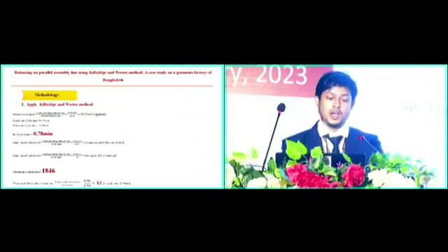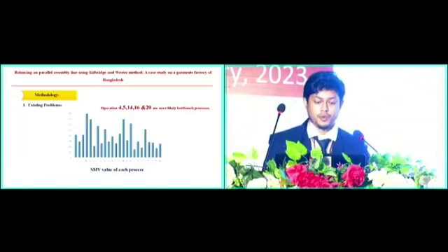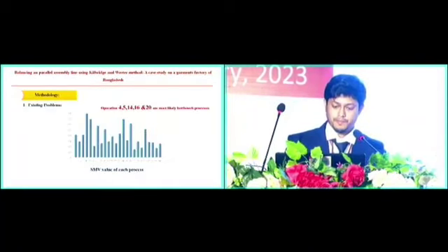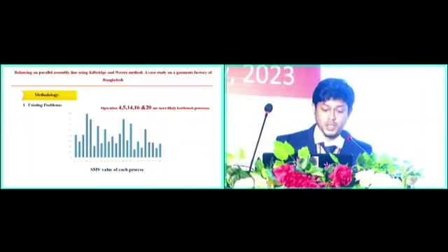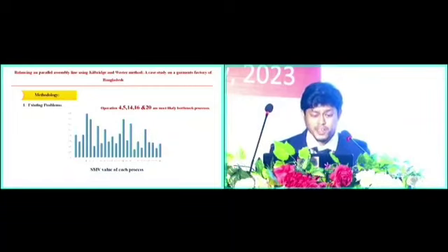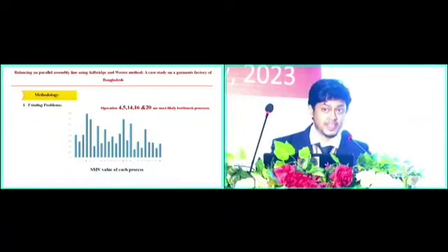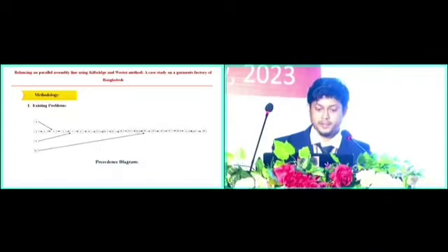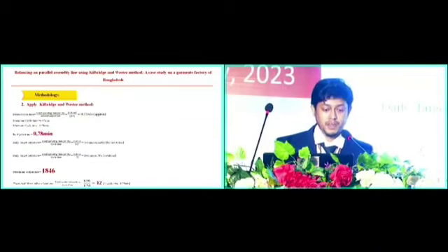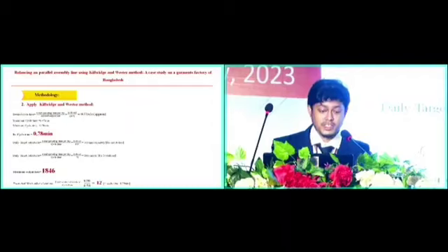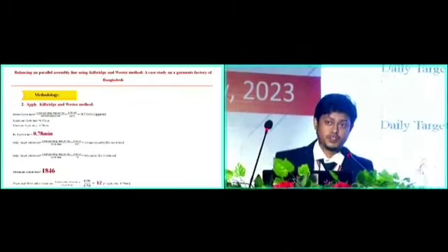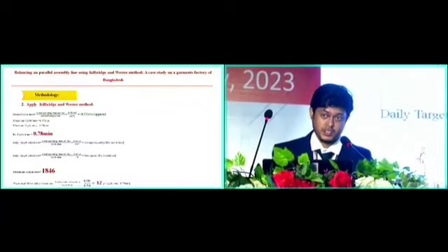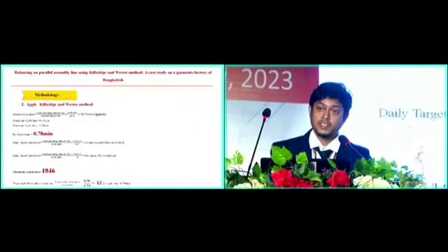But in my process, here you can see in 24 processes, the maximum bottleneck process is 4, which is almost 0.78. Below 0.8, which is almost 0.78. So the minimum cycle time is 0.78 and the maximum cycle time, which I have calculated from summing all the processes, is 8.97 minutes. So the cycle time will be 0.78 minutes.